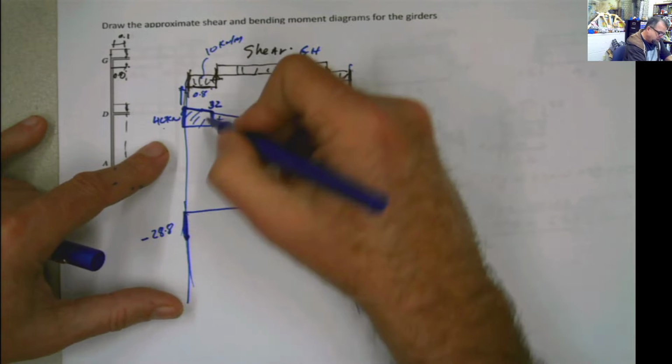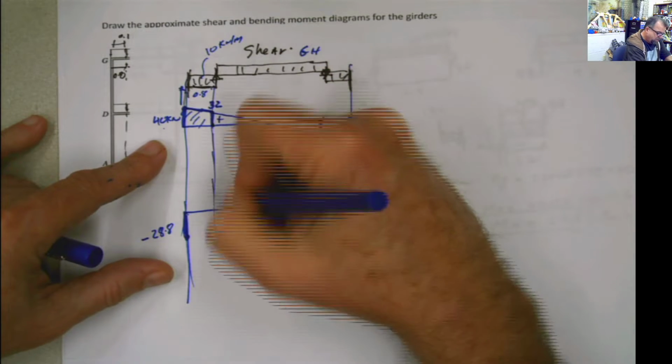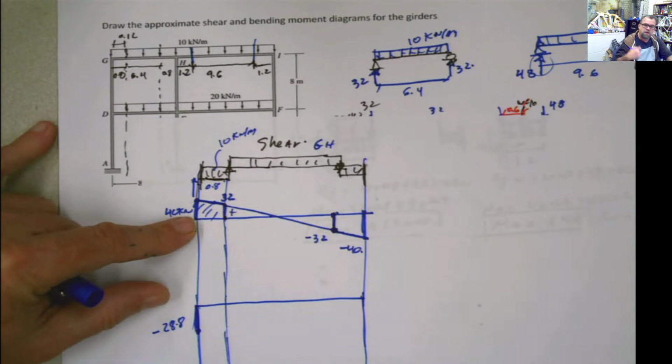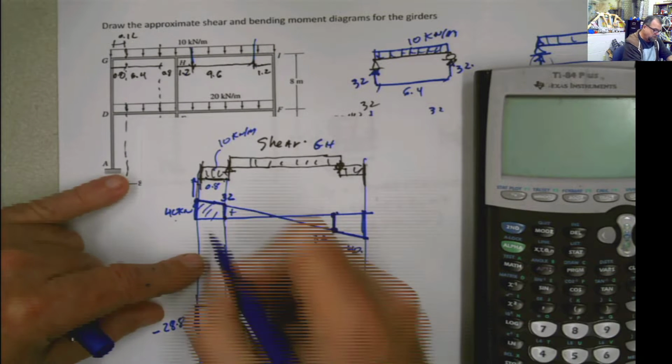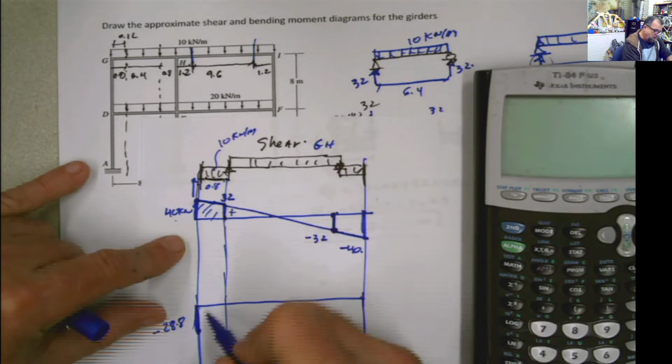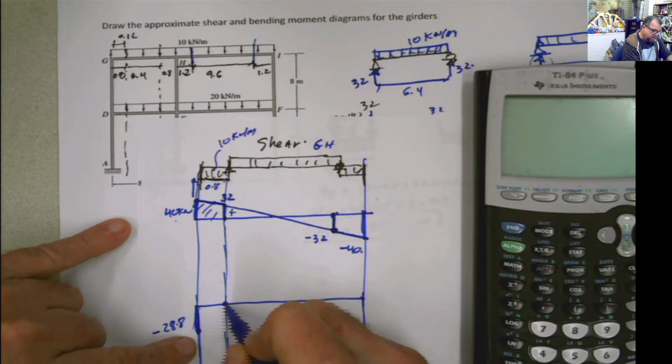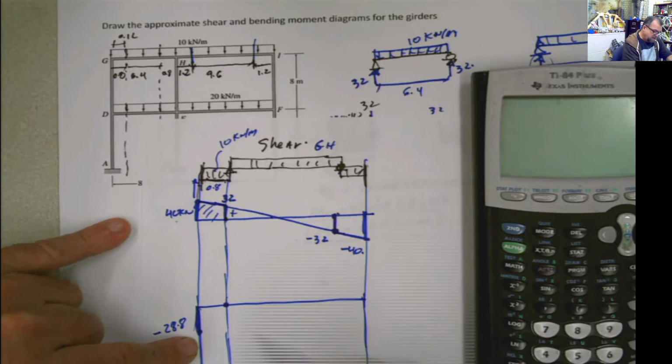Now let's do this point just for the sake of showing what is happening. That point is the point that we assumed the inflection point was, and we determined that, and we converted this with the inflection points. So this is 0.8. Well, if I want to find the moment at that point, it should be 0. Let's see if that is 0.